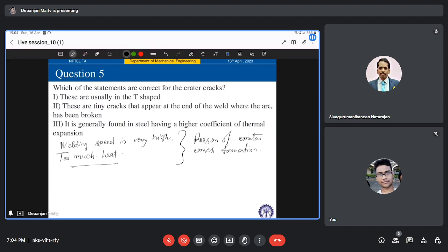And how can I stop my crater cracks from welding? One of the most important things is to make sure that you have enough power going into the weld. If you're using arc welding, this means making sure that amperage is high enough, right? And you also need to make sure that you're not welding too fast. This can be a difficult balance to strike, but it's important to find the right speed for your weld so that the pool has time to cool properly.